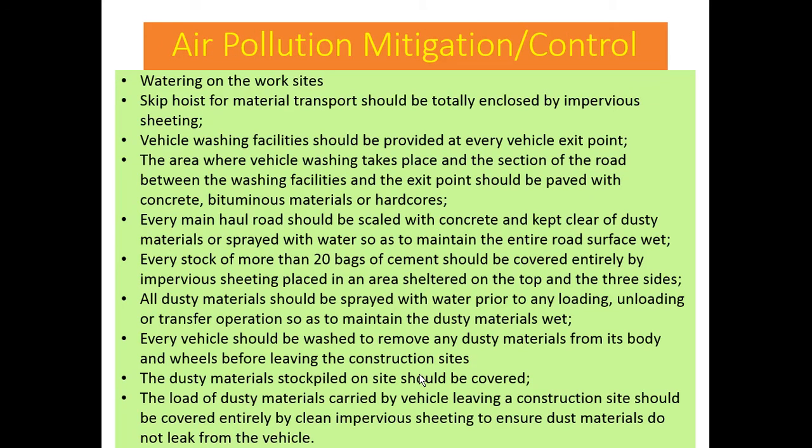Okay, this is the mitigation you can do to control for the action. Watering on the worksite, because for dust, this is to control dust. Skip hoists for material transport should be totally enclosed. Any open area should be closed, to reduce the particulate matter.